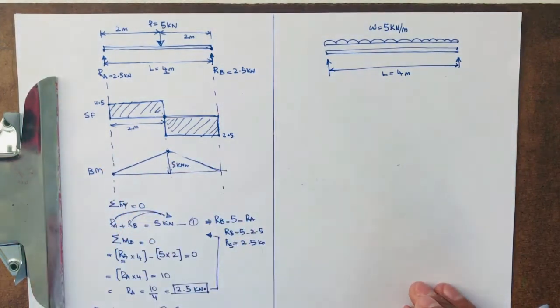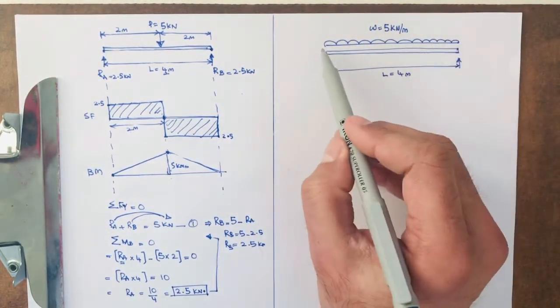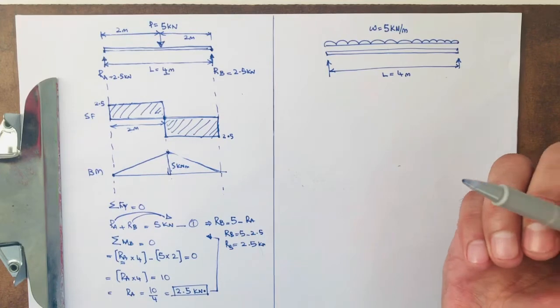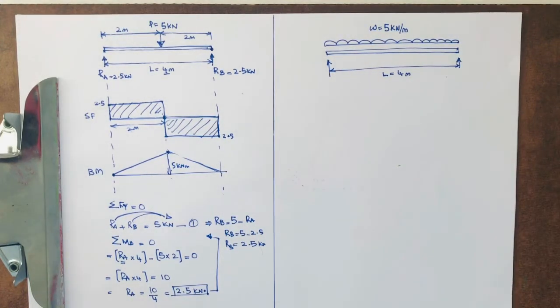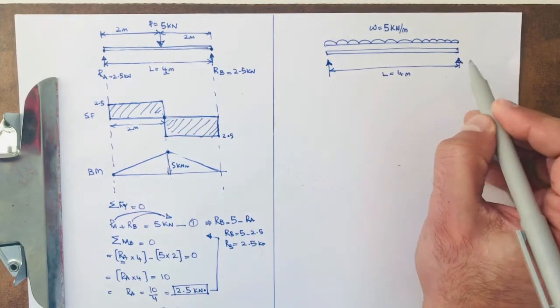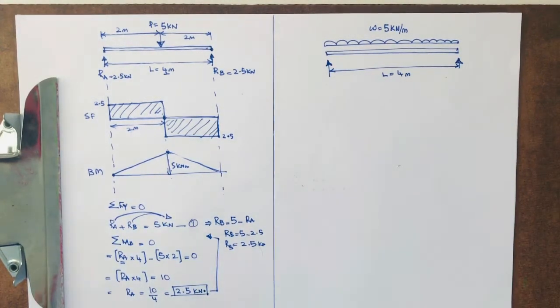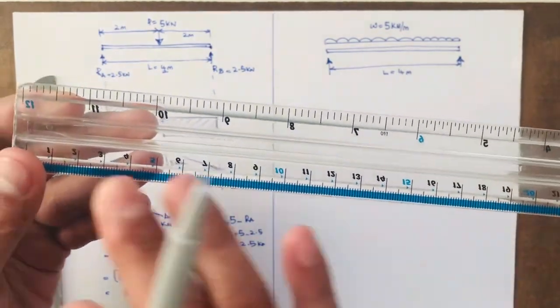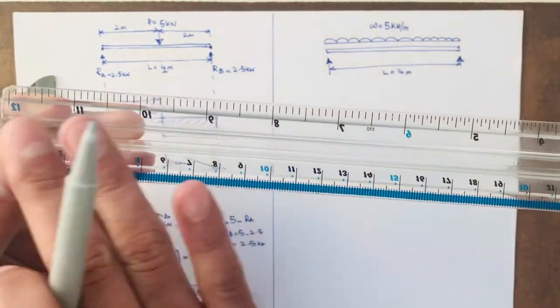So in this scenario, obviously we know the load is UDL, so this is a slightly different scenario for the bending moment, which previously we said was PL/4. In this scenario we would have a different formula, but first things first, we need to find out the reactions at the end, and we can again simply use the summation of the equilibrium equations, or alternatively, as said previously, if the beam is simply supported and we have a UDL, which is a uniformly distributed load throughout the length.